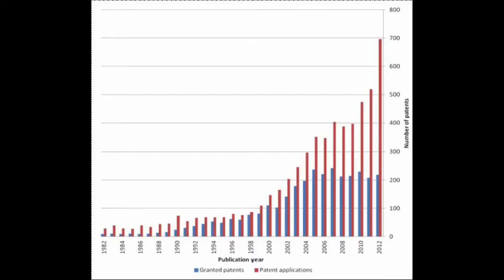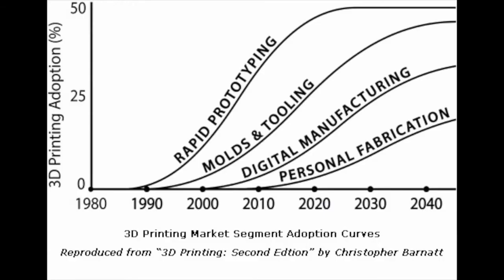It uses a vat of liquid photopolymer resin and an ultraviolet laser to layer the object. Every layer, the laser beam traces a cross-section on the surface of the liquid resin. When exposed to the ultraviolet light, the pattern traced is cured and solidified, joining the layer below it. As each pattern is traced, an elevator lowers and a resin-filled blade sweeps across the cross-section, recoating it with fresh material. In the 2000s, a working 3D printed kidney was created, and in 2008, a printed prosthetic leg was created.